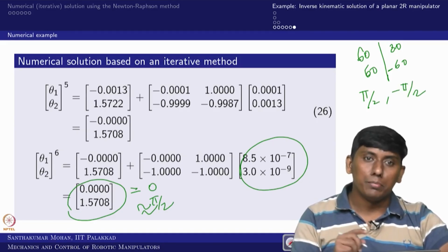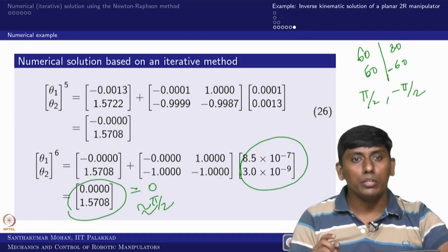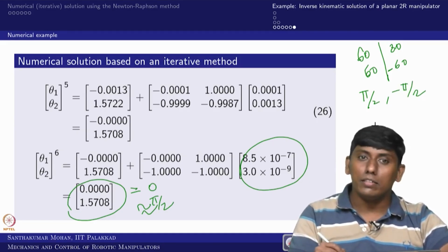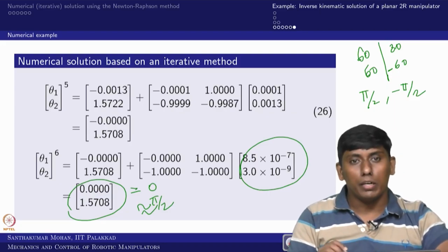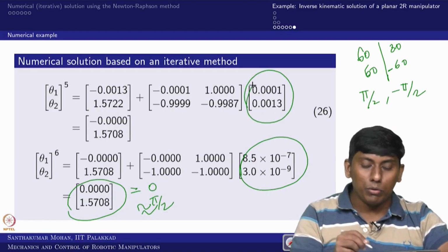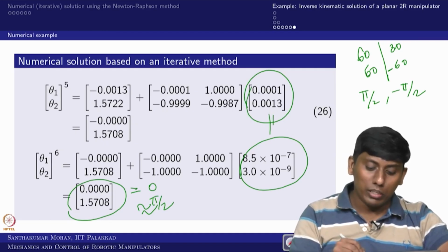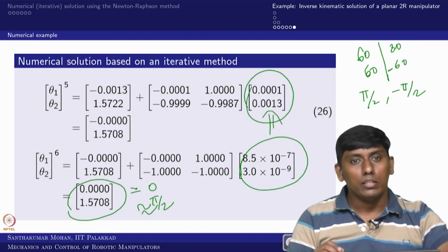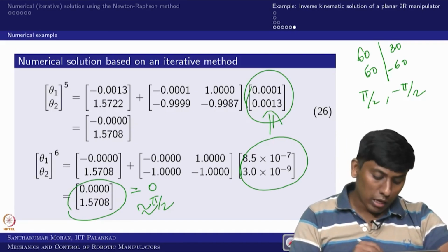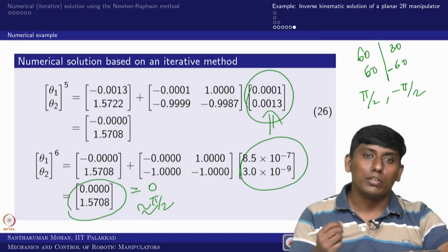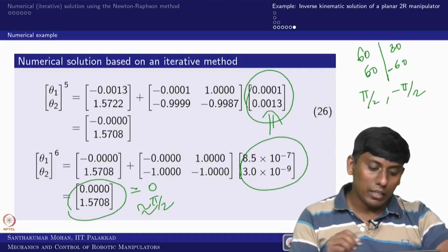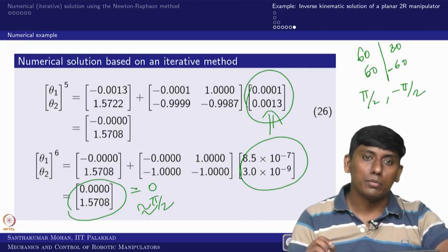Okay. So only one condition I am putting here. Whenever you are substituting, you substitute in a common unit. So you substitute in radians, okay, because your Jacobian matrix would be of a different order, and you are giving your position values in meters, so better you use radians everywhere. Now these values are in radians, so you can convert that into degrees whenever you require. So with that we end up with the Newton-Raphson method.